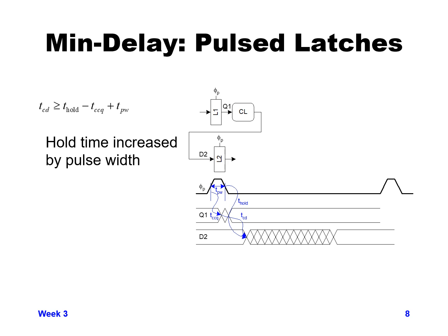So in this particular case, this is one of the greatest dangers of using pulse clock or pulse latch designs: you have a pretty great danger of getting min delay problems in pulse latch designs because of this factor of the size of your pulse width increases the hold time that you have to worry about. And I've actually seen pulse latch designs that require a lot of work to try and fix issues related to this.